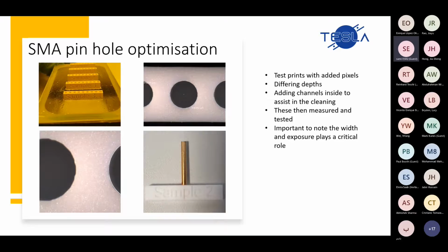However, it was not taken into account that the filter section is much wider than the test wedges. And these test wedges undergo less overpolymerization, and due to this, the holes shrink even further on the filter. So it's important to take into account the final width of the part that you're trying to print, otherwise you end up with inaccurate results.